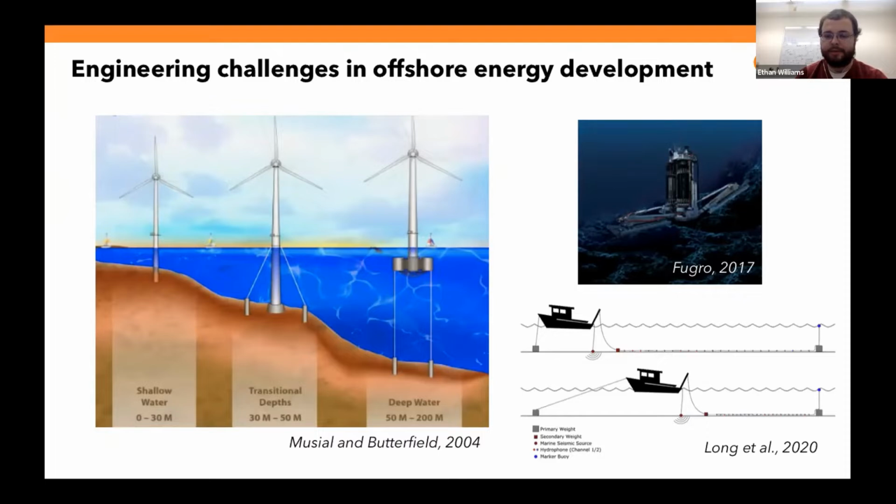And this can be quite expensive, to measure in situ parameters like shear modulus or shear strength. You need to do either some sort of geotechnical coring using a quite expensive apparatus, or you could do some sort of multi-channel analysis of surface waves to get a VS profile, but that also then requires an ocean bottom source and an ocean bottom array of hydrophones. And distributed acoustic sensing, using cables that are already installed at the seafloor or can be easily installed at the seafloor temporarily, seems like a relatively natural improvement in these methods because it dramatically decreases the logistical complexity and associated cost for these surveys.